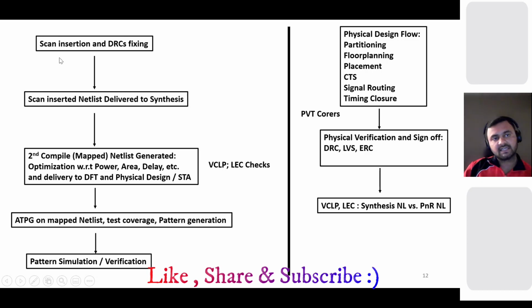Since you receive the gate level netlist here, you will perform the scan insertion and DRC fixes. Whatever DRCs there are with respect to the scan, you will fix them here, and you perform the scan insertion. Then you will get the scan inserted netlist, and again you have to deliver it to synthesis. Now it is called map.